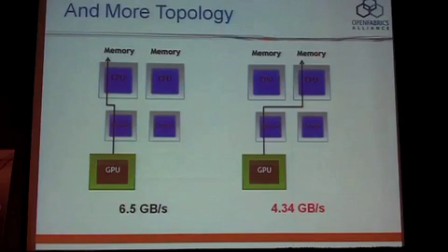The reason you guys are interested is because, you know, we're already at 16 lanes of PCI Gen 2. We'll be at 16 lanes of Gen 3 once Gen 3 is widely available. You guys are only like one multiplier behind us. So IB cards currently, a 40 gigabit IB needs 8 lanes of Gen 2. As you go to FDR and EDR, you're going to be pushing the same bandwidths that we're pushing, and you're going to hit the same bottlenecks that we're hitting.